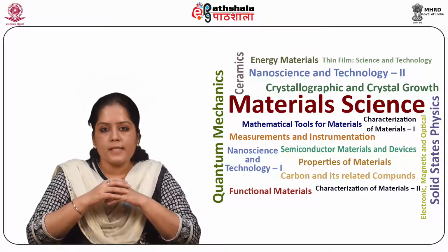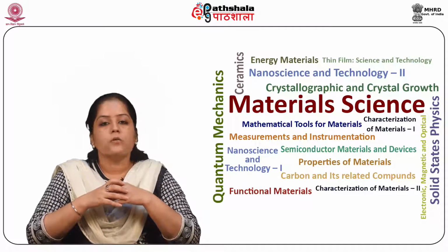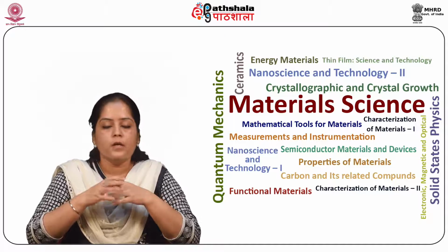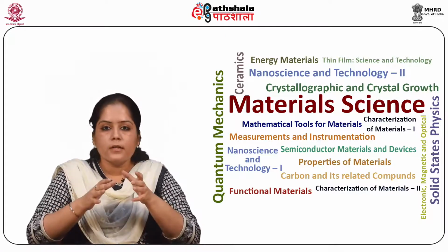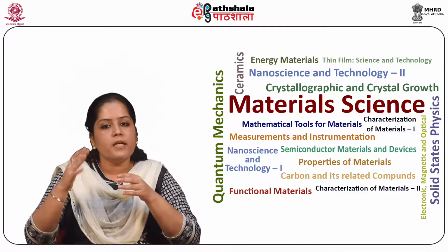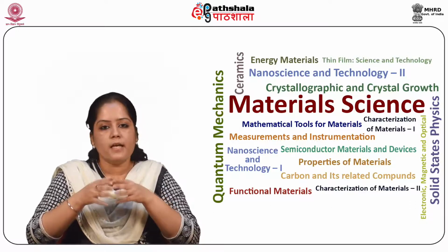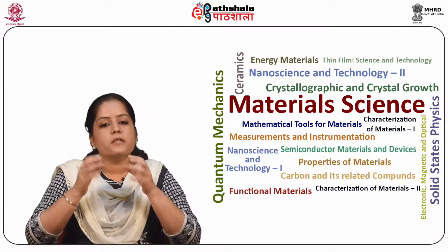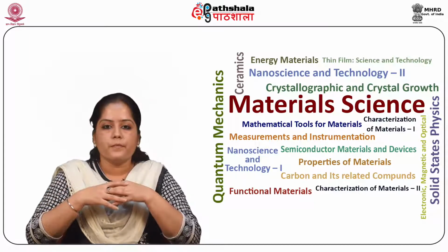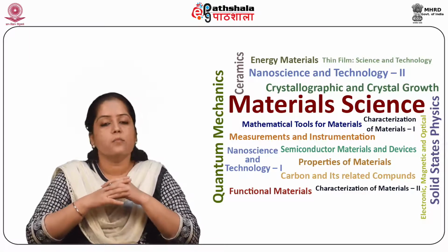The fracture of ceramics initiates from pre-existing flaws in the ceramics. So in this module, we first discuss the source of these flaws. Fracture toughness is an important and critical property of structural ceramics. It is generally very low in these materials. So a knowledge of the toughening mechanism is important to design the ceramics with increased toughness. So this is the thing which we are going to discuss in this module.